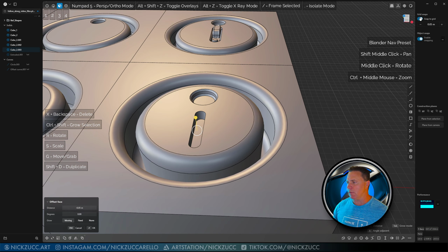If I go this direction, go from there to there, this seems to work. This can work in your favor a little bit later, but you can see it generated this curve part here. And actually what it's doing, it's building tangency between this curve and this curve. So it's building a curve that joins it together, and mathematically it's perfect for how it flows into this curve and then flows into this curve. So that's a little bit important for later on if you do things with the surfacing.